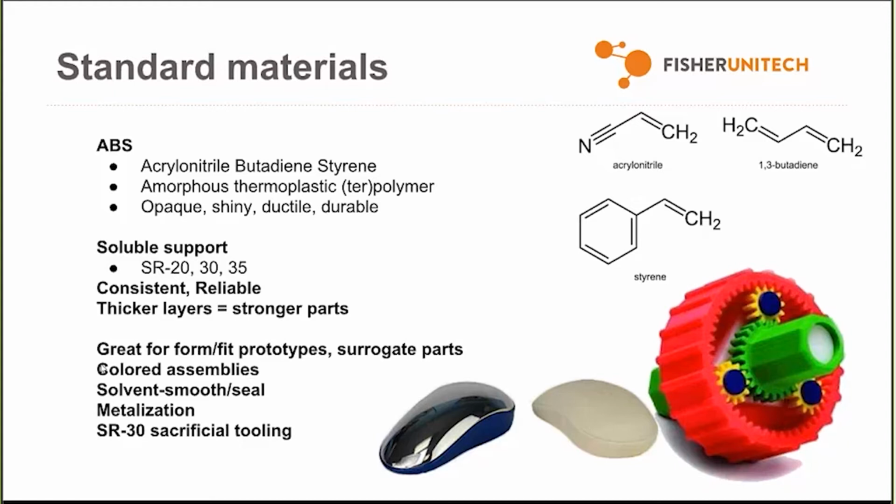Some examples. ABS parts can be basically stand-in parts for actual parts. So if you, for example, pause a sparse infill part mid-build and pour in lead shot or sand or pea gravel, you can build a part of accurate size and shape and weight, and then you can use that part to do things like teach robot positions with full kinematic accuracy. And you can do all that before you have actual steel parts in hand.